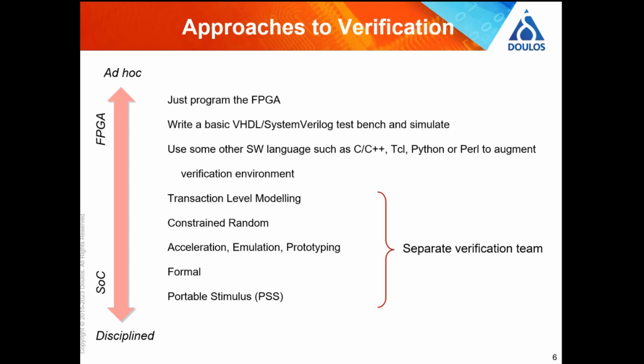So you say, here are all of the data sources, here are all the data sinks, only three of them can work at once, and this can't happen when that happens, this can't happen until that happens, this can happen at the same time as that, but only when this is finished. You give it all sorts of rules like that, and what it does is go and write the test itself. It randomly generates different scenarios, like, let's try sending data from this CPU to that network interface and at the same time from the camera to the, etc., etc. Really, really cool technology as well.